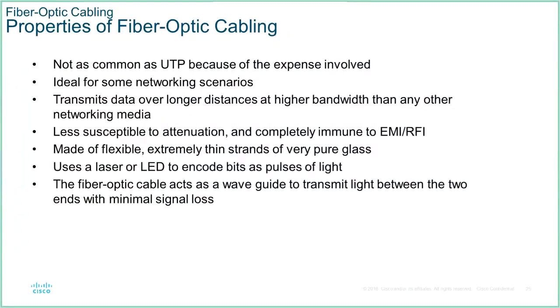High traffic areas, as in underneath desks, where things can come into physical contact with cabling, can cause damage. So fiber optics are more prone to mechanical damage than copper cables. And they do not bend very well because the early ones were basically pure glass.